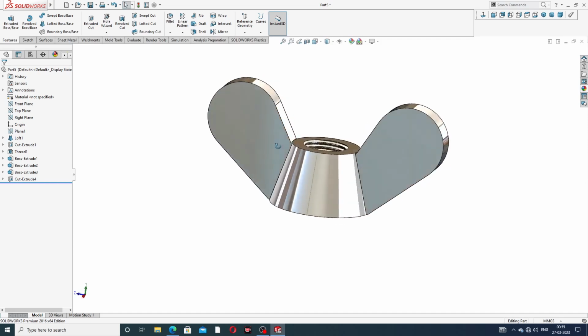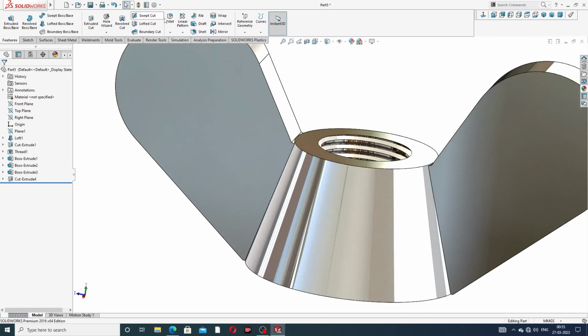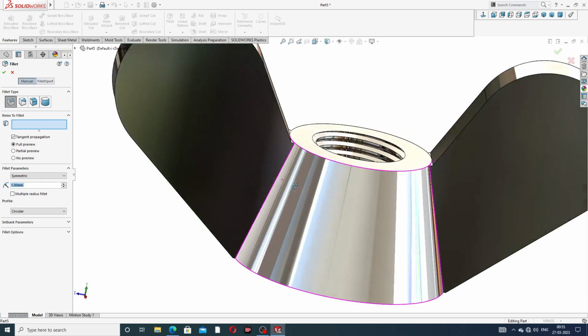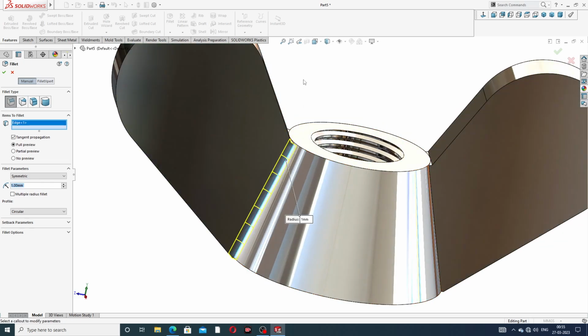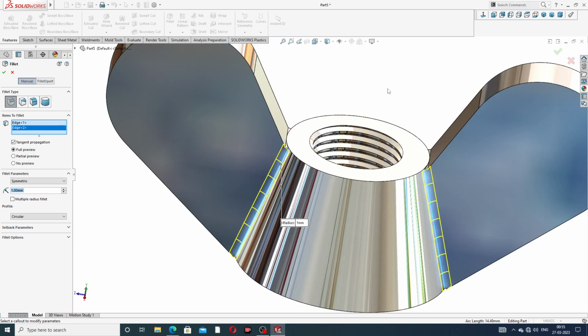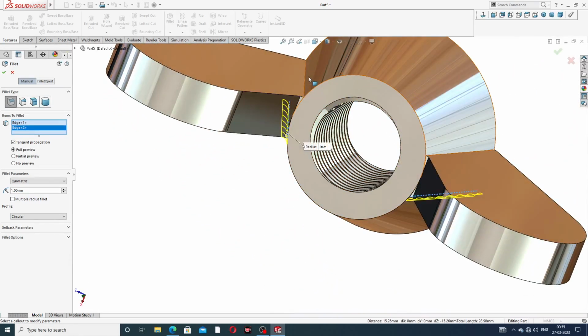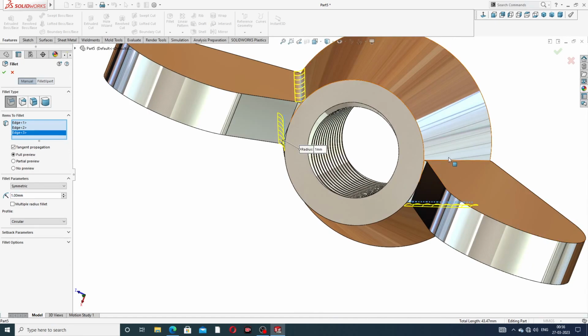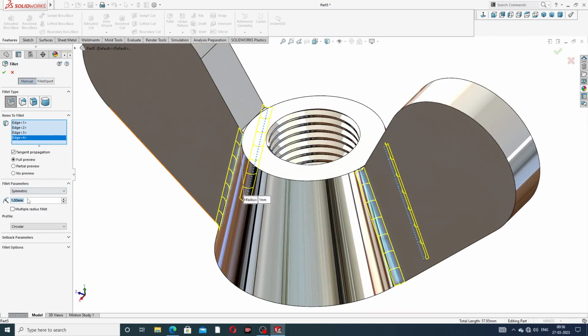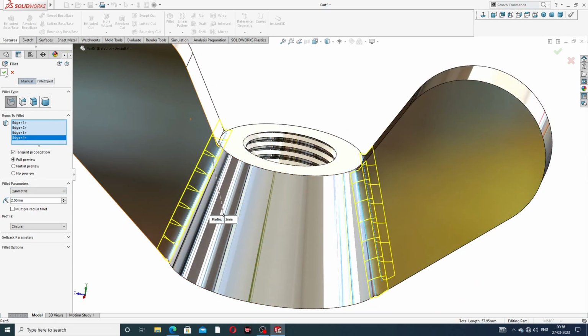And next, at first select a fillet. Fillet is 1 millimeter, and select this, okay, and this to this, select this and this, and 2 millimeter is better. 2 millimeter is also, 1.2 is perfect.